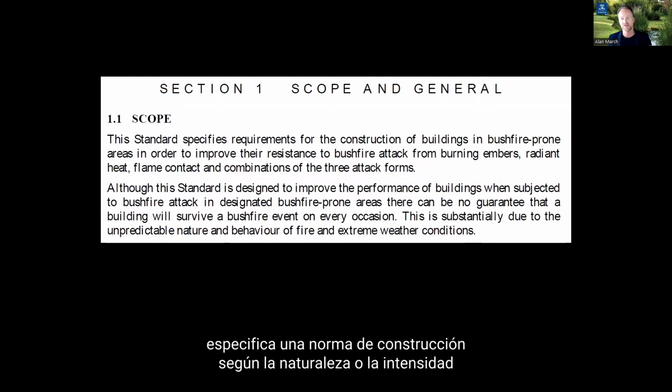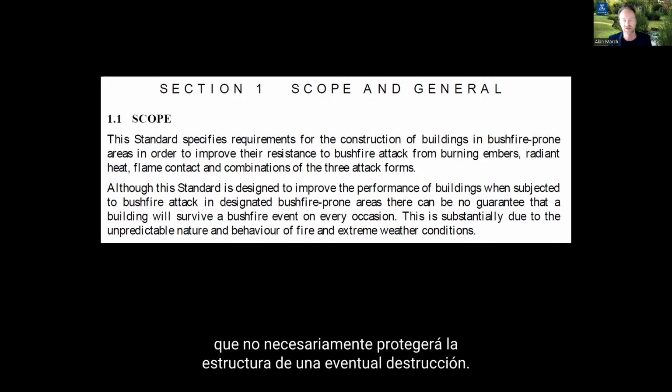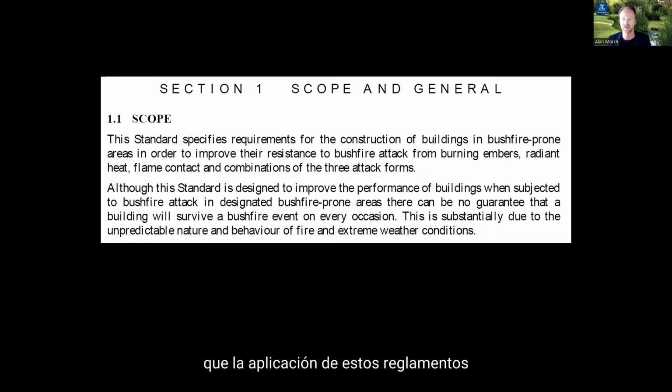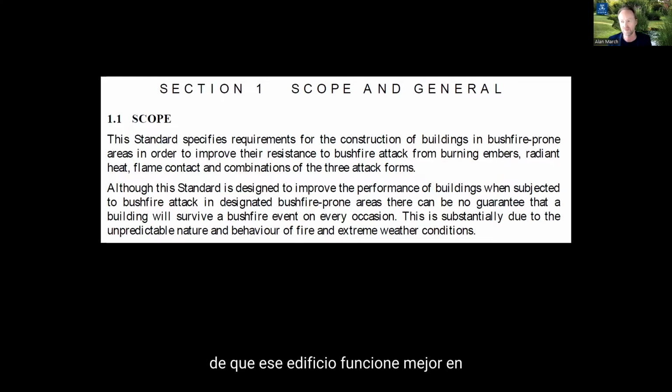The main thing it does, it specifies a construction standard according to the nature or the intensity of the wildfire risk in that particular location. There is an assumption that it will not necessarily protect the structure from eventual destruction. However, the other assumption alongside that that's implicit is that the application of these regulations will significantly improve the chances of that building performing better under wildfire attack conditions.